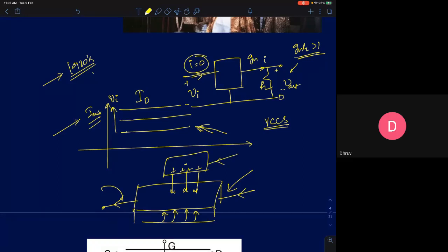That was the idea, but there was a problem that these field lines were not penetrating the semiconductor to bring the electrons to the surface. So that's when they introduced an oxide, and the problem was resolved. In between the metal and semiconductor, when they introduced an oxide, the field lines could penetrate and then electrons could be brought to the surface.